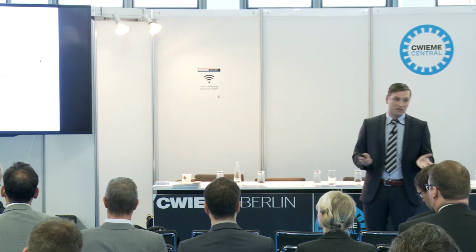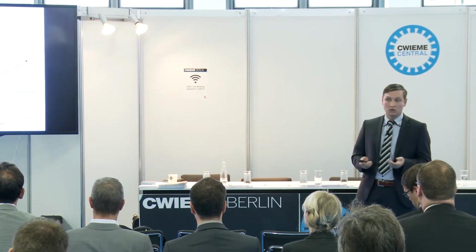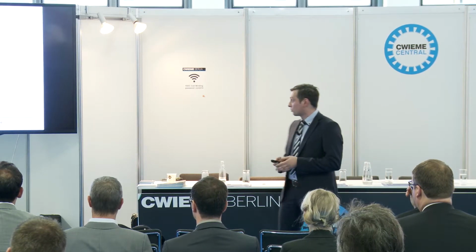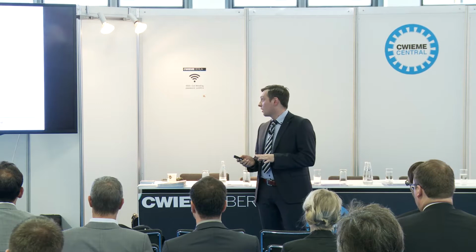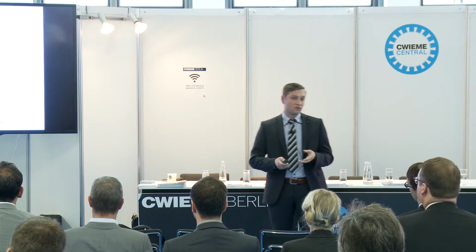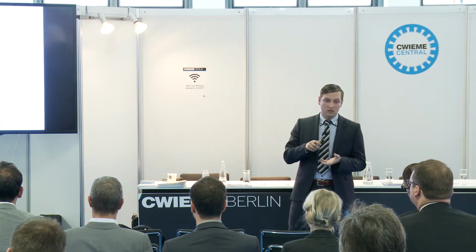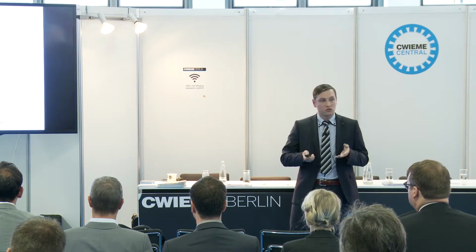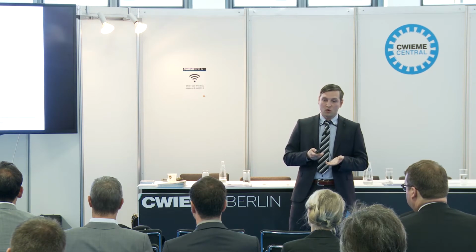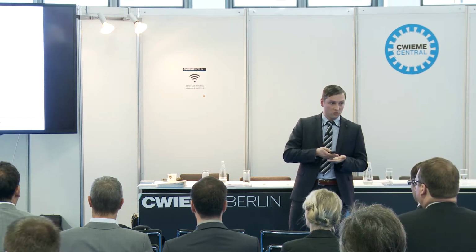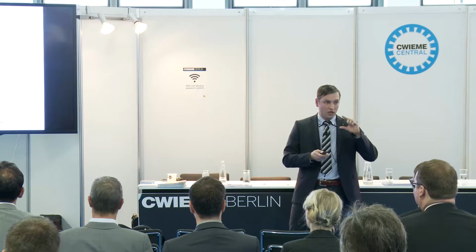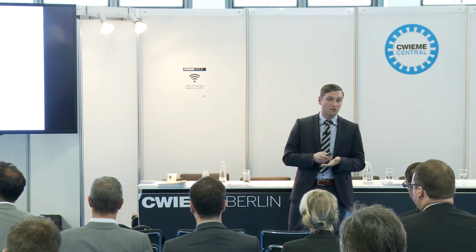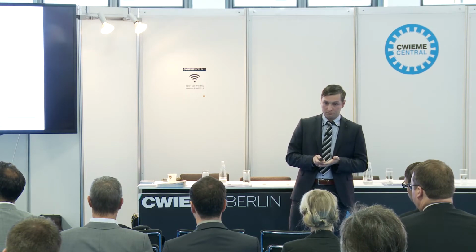So, but how does laser remote cutting actually look like? Let's have a look at the process principles. We start with the laser fusion cutting. A conventional cutting machine consists of a cutting head with a nozzle having a certain standoff to the workpiece of between 1 and 2 millimeters. When the focused laser beam strikes the material, the whole volume of the cut curve is heated up, molten, sometimes vaporized, and driven out by the gas jet.